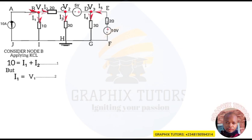Similarly, I2 is equal to the voltage from where I2 is coming from, which is V1, minus the voltage to where I2 is going to, which is V2, divided by the resistance in between them, which is the 2 ohm that we have there, right? I will term that my equation 3.